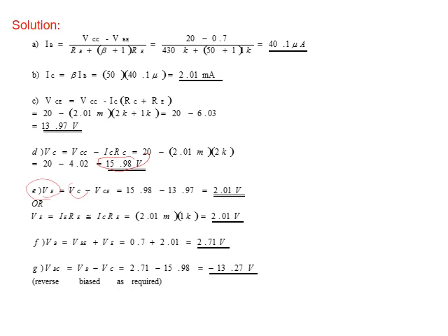VE is VC minus VCE. We have VCE, we already got it here, as you can see. VC, we got it here. Just substitute, we got V emitter. Or we can find I emitter, because I collector is similar to I emitter, it's the same. So R emitter by I collector gives me the same voltage.